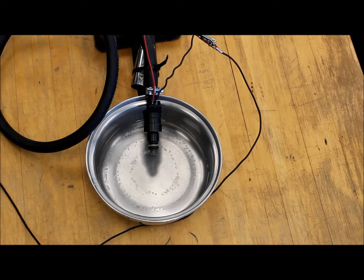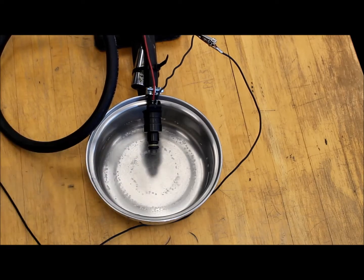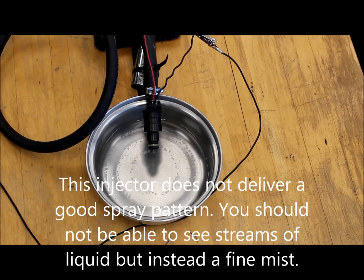I have everything set. I have my pressurized hose hooked up to the inlet of my injector. I have my power supply connected to the electrical connectors on the injector. And I'm just ready to turn that on. We're going to see if we can observe any flow out the end of the injector there. I put a little bit of water in the bottom of the pan. Hopefully this injector will create some waves and make it a little bit easier to see. So let's turn it on and see what happens.